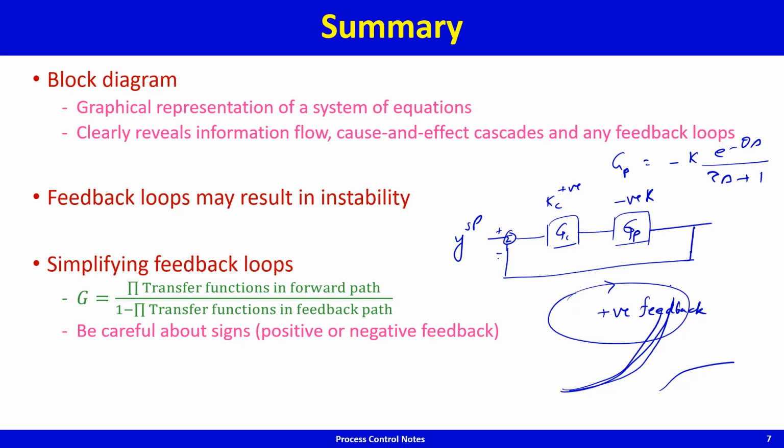So in this case, because the process gain is negative, Kc will have to be negative. And if this is negative, then the sense of the feedback is going to be negative times negative is positive. Then you go back around here and come here negative. So positive times negative is negative. So then this is negative feedback, and now you are doing control.